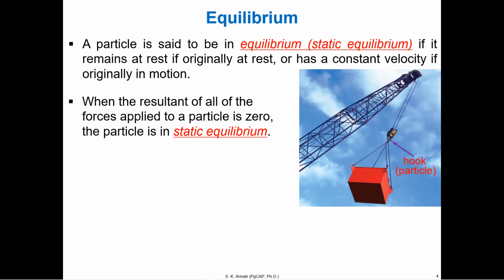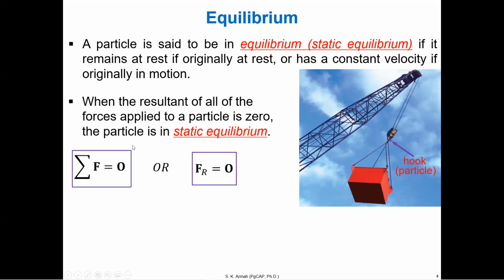If you remember, I said the equilibrium of a particle has to do with Newton's first law. And what's the main condition? We are neglecting the size, so it can only translate in a particular line or axis. So the sum of forces should be balanced. Or we say the sum of forces in any direction should equal the sum of forces in the opposite direction. Vectorially, in general, we say the sum of the vector forces is equal to vector 0. Or the resultant force, as we should say, equals 0.